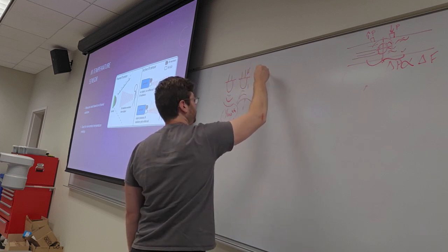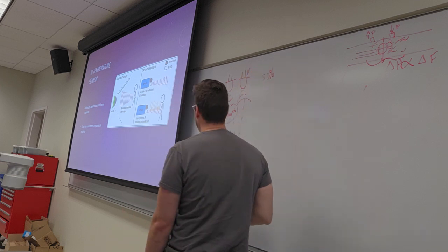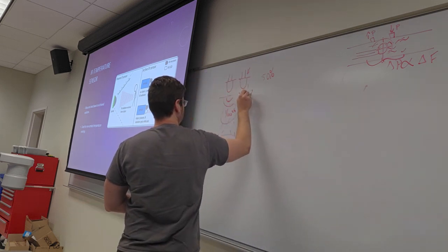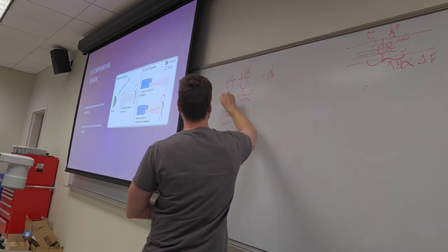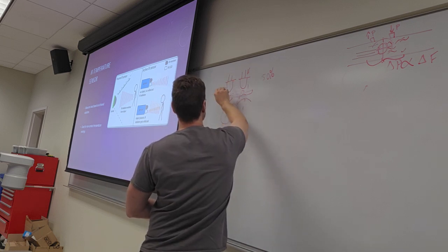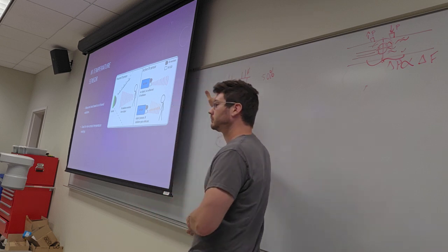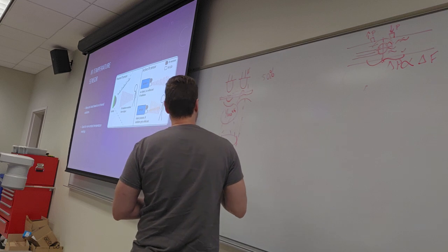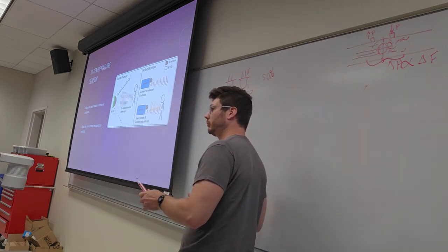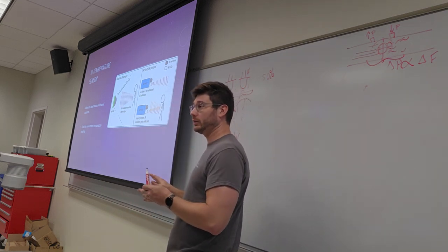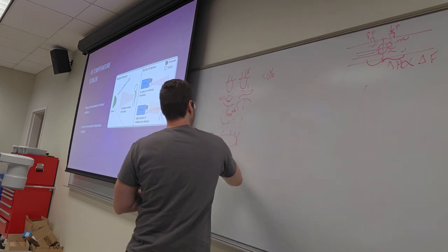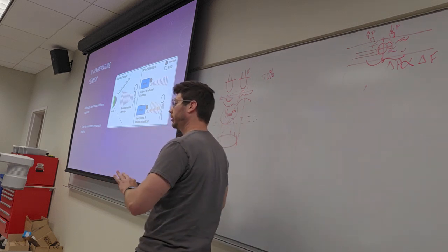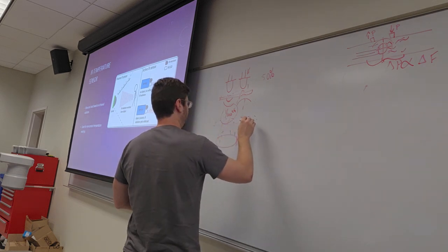Okay, say I saw 50% of the maximum that I expect to ever see, right? If you held a super white piece of paper against here that was ultra reflective and 100% of the light from this went into that, that would be 100%, right? So using this, we can have a very simple distance sensor, assuming something is moderately the same color. If we have an object here that is mildly reflective to infrared, which most things are, regardless of color, okay? We're in the infrared band here.